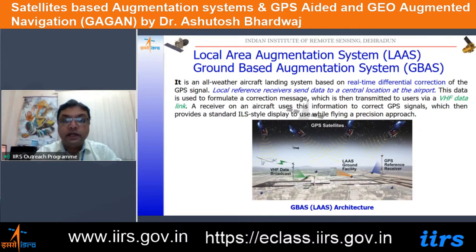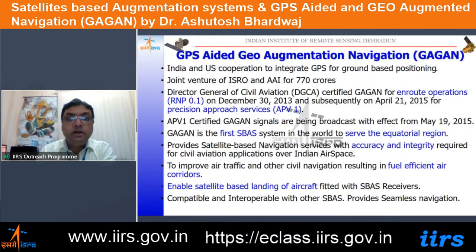If they are near to the reference station, the correction parameters will remain the same. If they are far from it, the weather conditions may be different, and then the ionospheric correction or other correction parameters which have been sent to the aircraft or the user may not be as accurate as they are for the neighborhood region of the reference stations.